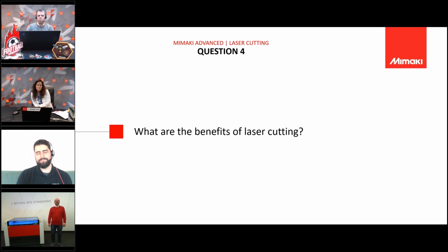Yeah, I would add two main benefits. One is throughput. If you look at cutting speed and overall processing time, when you cut acrylics or many other substrates compared to either a knife cutter or a router, you're just much quicker. We had customers who were just surprised to see what kind of boost they got through laser cutting. So they could lower their prices to end customers and start getting much more volume in orders because of their new productivity and new price point.